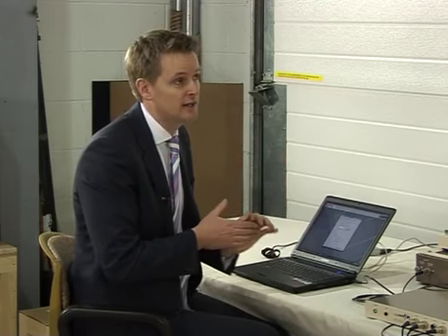Note, you must always have the triaxial cell out of the load frame, as we have here, for risk of crushing whatever you have in the way of the RAM.